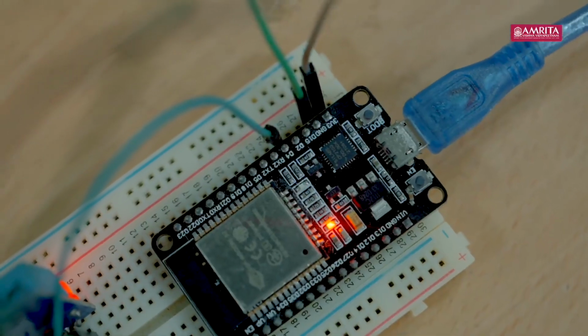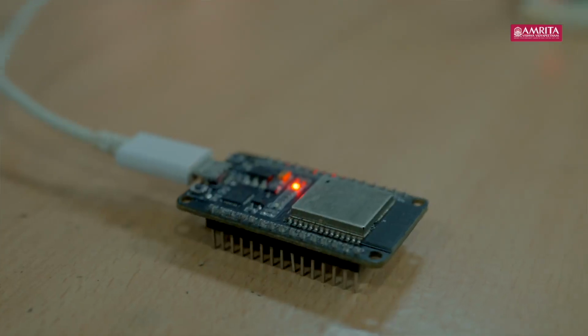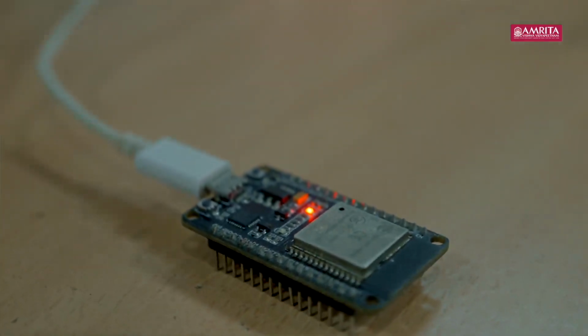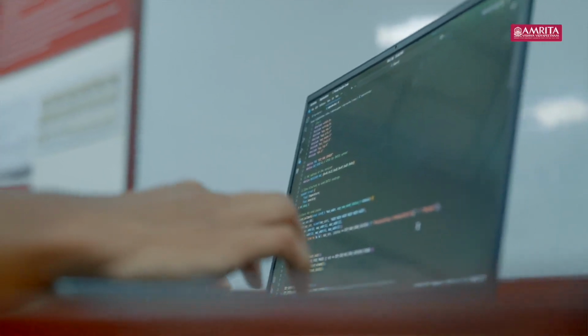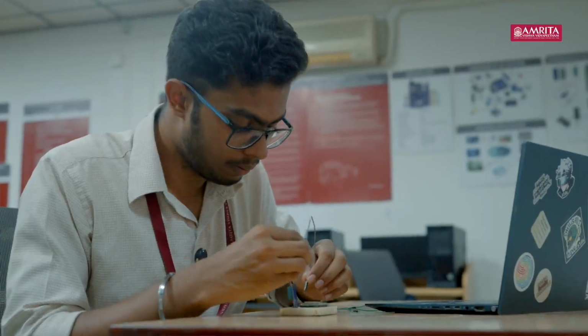There are some regions where we are not able to directly integrate this type of communication link between devices. We can provide a communication link where we are not able to access Wi-Fi directly, or even use Bluetooth, because when you are using Bluetooth, the network becomes much smaller compared with the ESP-NOW protocol. In ESP-NOW, we can integrate many more devices, because there are more options such as one-to-one, one-to-many, many-to-one, and we can also do a broadcast option.